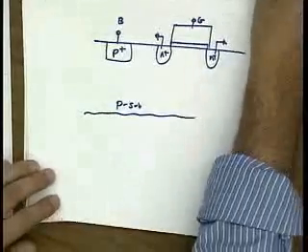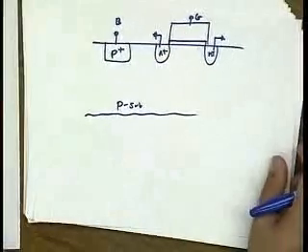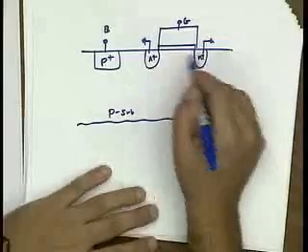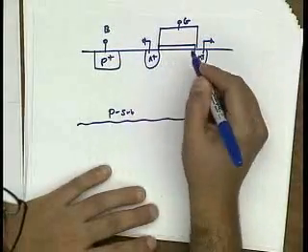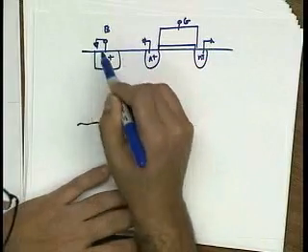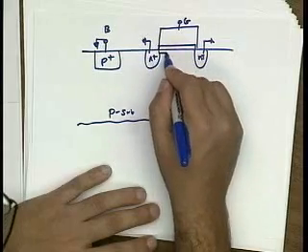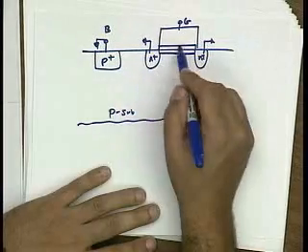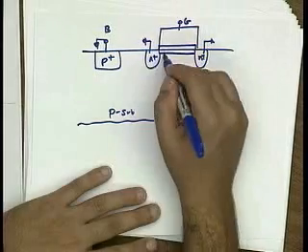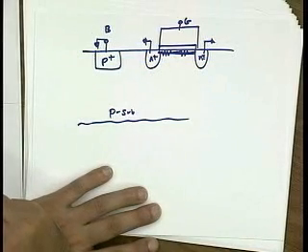Well, if you basically think about the Q of this structure, if you're in inversion mode, then the quality factor, so let's say that this is also grounded, so this is a capacitance to ground, then in inversion mode, you'd form a channel here, and the electrons basically would flow to ground through here. And so basically the resistance of this channel would determine the Q of this capacitor.